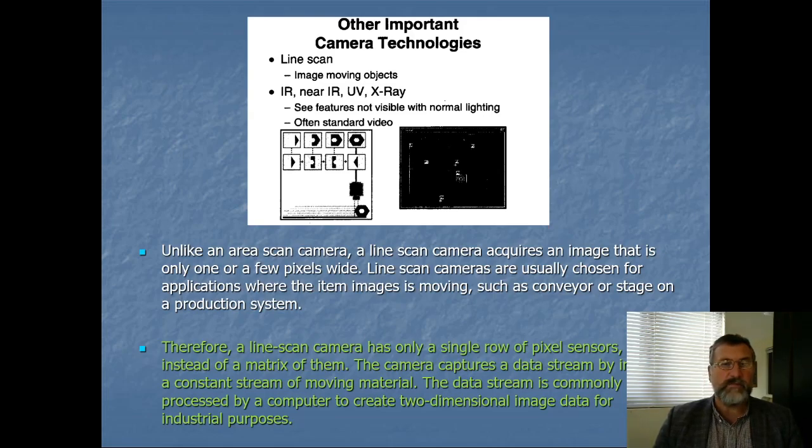So if the conveyor changes in speed, that will be accounted for because the encoder is measuring the actual position of the conveyor all the time. And you only need to flash a light every time you grab an image, so you can just use sort of LEDs that come on at that time. And it works pretty well in many industrial applications for objects coming along conveyor belts.